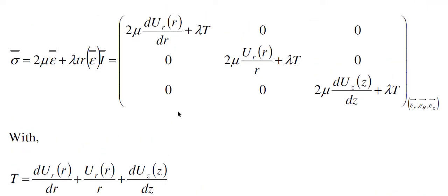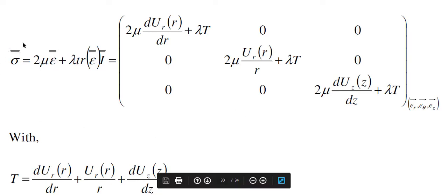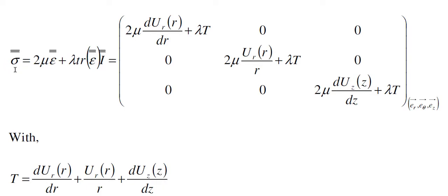Now, it's to note that this constitutive equation relating the stress state to the deformation state is only applicable when epsilon is kinematically admissible. Only in this case can the stress tensor sigma be obtained from the deformation tensor epsilon.